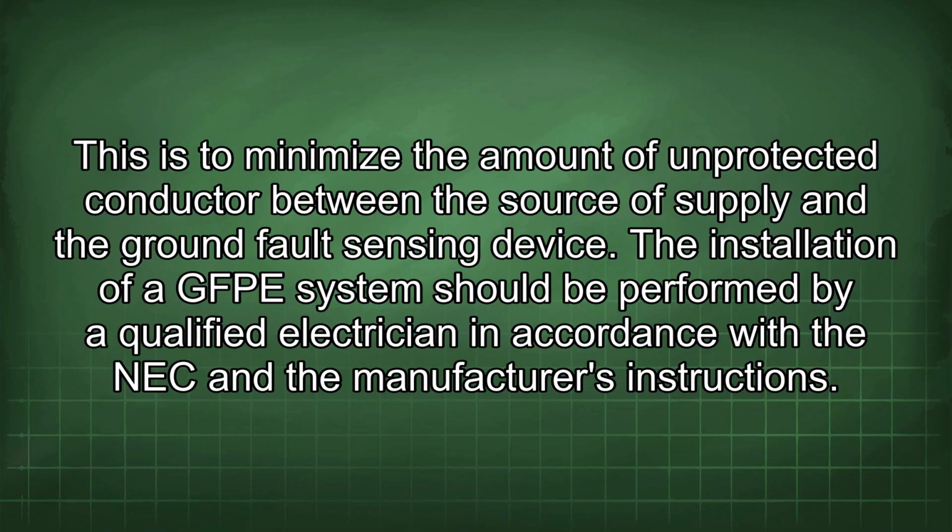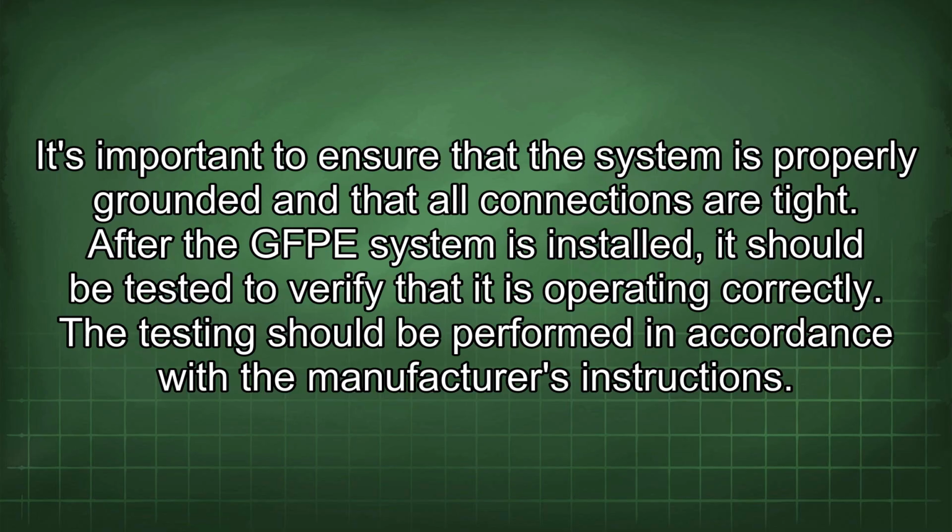The installation of a GFP system should be performed by a qualified electrician in accordance with the NEC and the manufacturer's instructions. It's important to ensure that the system is properly grounded and that all connections are tight. After the GFP system is installed, it should be tested to verify that it is operating correctly. The testing should be performed in accordance with the manufacturer's instructions.